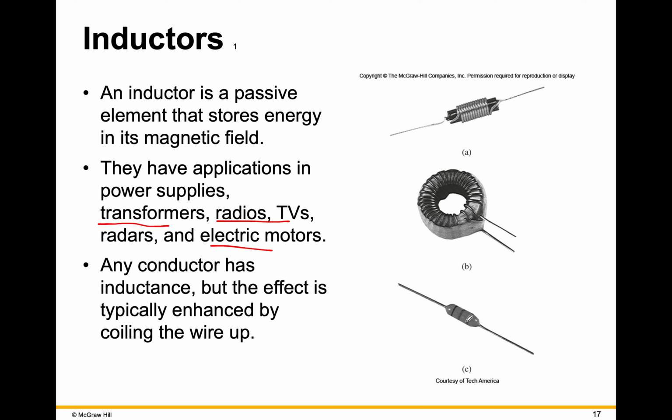In this class, we are dealing with inductors that are linear elements. What's pictured here, if you look kind of in here, that's a magnetic core. Inductors wound around magnetic cores are done so for some really good reasons, but as soon as you do that, your inductor and its behavior becomes nonlinear because you've introduced a magnetic energy storage material.